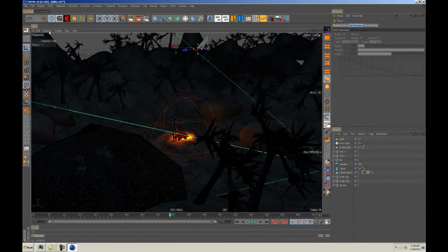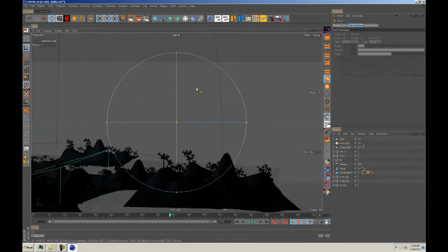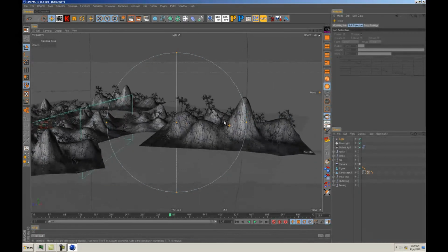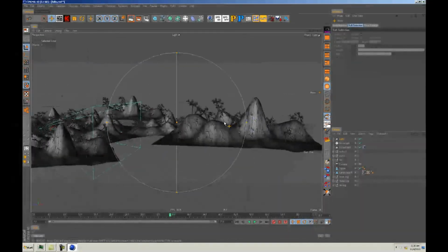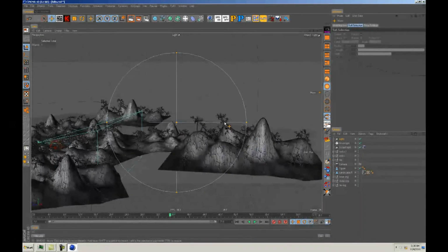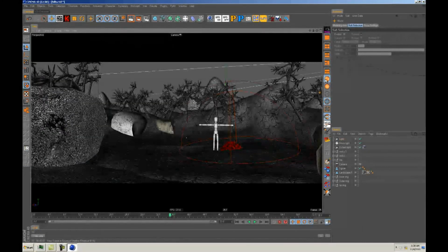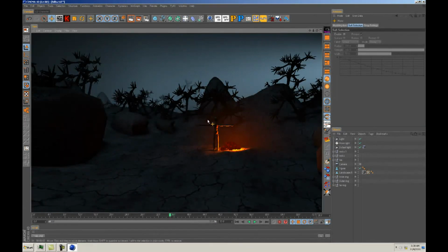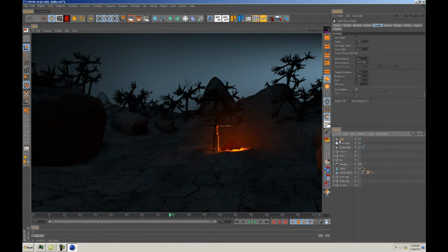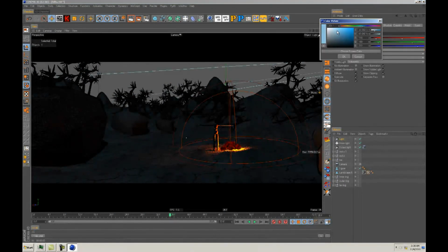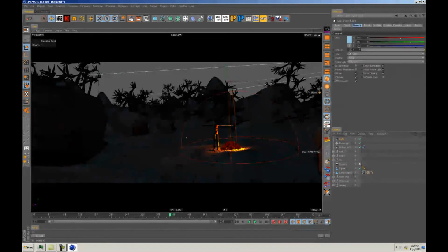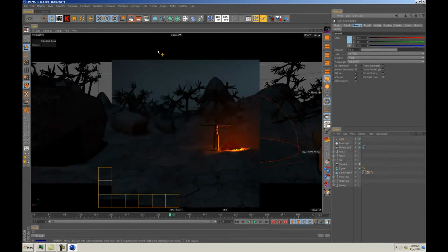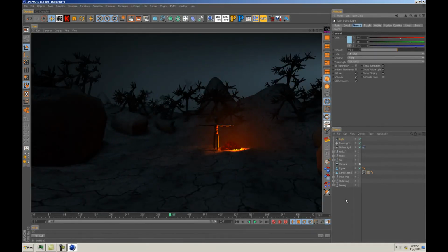So we can go to our other perspective view and go link active objects and actually look through the light. Let's do this, I can see it better. Maybe this one closer, and then kind of like this. Let's see what that looks like. It's a little bright, and it looks like it has some green in it or something. It's at 100%. Let's try 56. That doesn't look that bad.